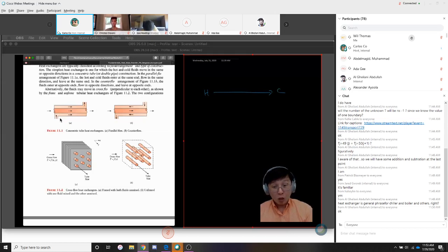On the outside you have inlets and outlets. Under no condition would you route hot water and cold water in the same direction. Or conversely, with a hot stream you want to cool down, you put in cold water and out comes hot water. Under no conditions would you have it going in the same direction.